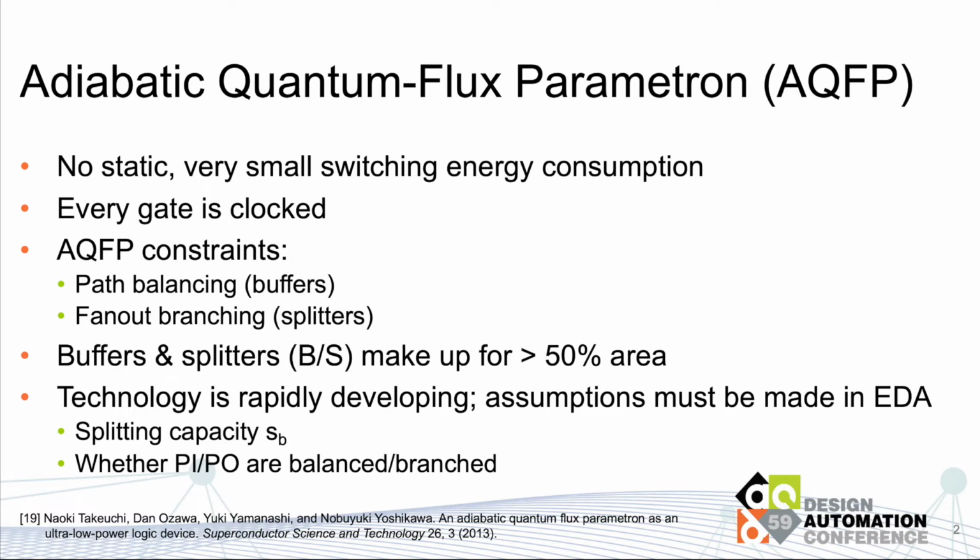AQFP stands for Adiabatic Quantum Flux Parametron. It is an emerging superconducting electronic technology featuring a very low energy consumption. In AQFP circuits, every gate is clocked, which causes an additional design constraint, path balancing. All paths in the logic circuits have to be of the same length, so shorter paths need to be balanced